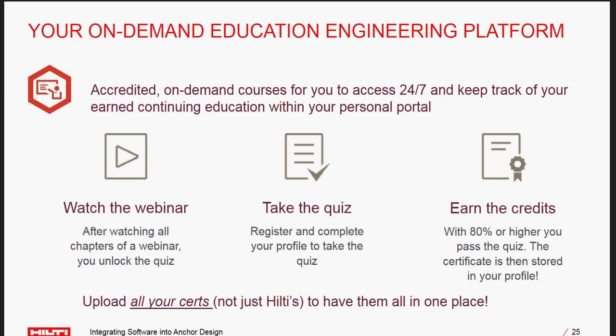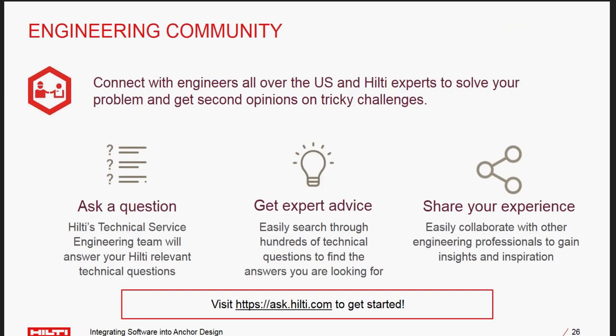It's going to default to optimized, which is trying to drive that utilization as close to 100% as possible. But if we wanted to use a custom embedment depth up to 20 bar diameters, because that's a limitation in ACI anchoring to concrete provisions, we can do that by selecting the user selected embedment depth. But because we are using the 7/8 diameter element, our limitation is going to be 17.5 inches.